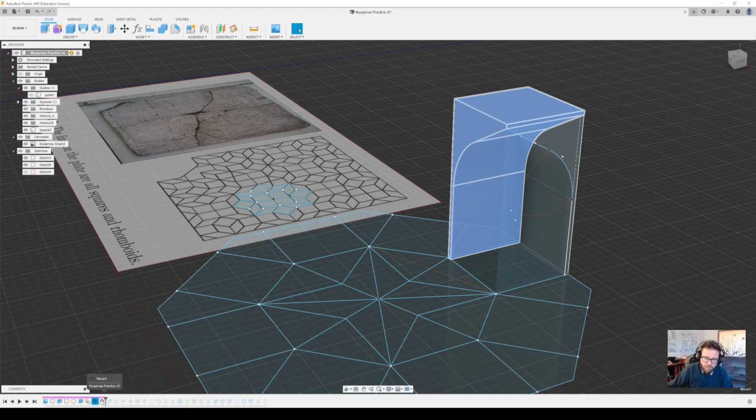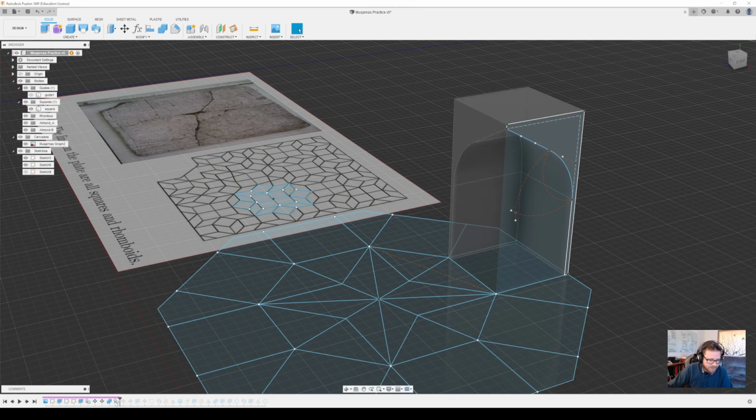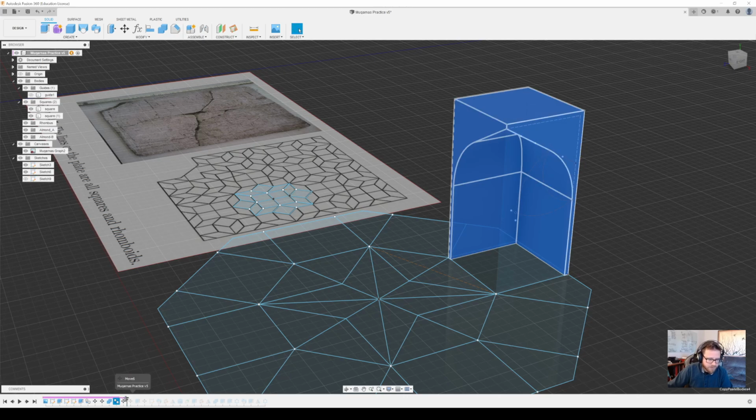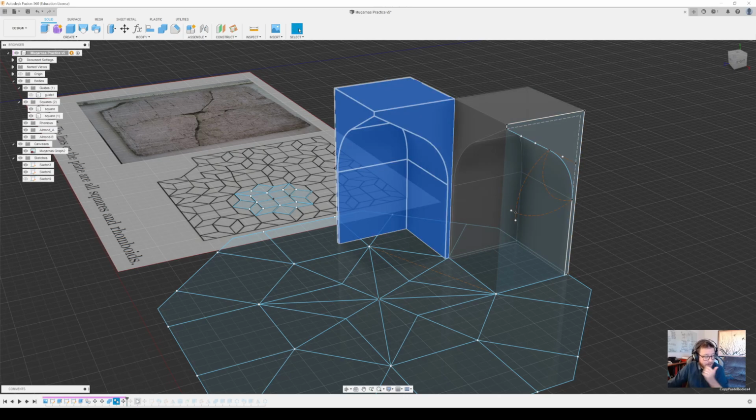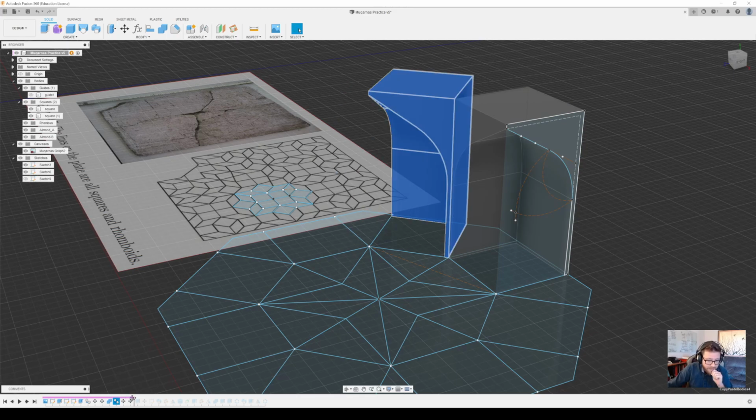And then I'm going to rotate it in, and I'm going to use this command right here, which is, you can see, the combine command. If we look to the left here, I open up these bodies. See, there's a square and I call them square and square because that's where they come from. These are being combined into one piece. And once I've got that, there's a lot of cool stuff that you can do with this. You can move this out and create a copy of it. You can rotate that out as we're seeing here.